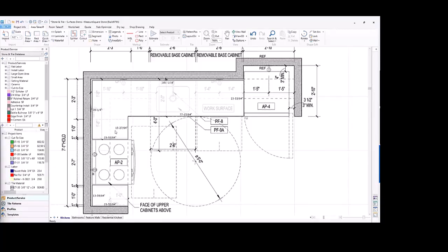All right. So next up, we're going to add another seam in this corner, and this time I want to make it a vertical seam. So I'll go ahead and use my splitter tool again and select vertical splitter this time. Then I'll go ahead and left click on that corner, wait for it to snap into place, and click. So now I've broken up my countertop into 3 separate pieces, which should make it easier to fit on a slab.